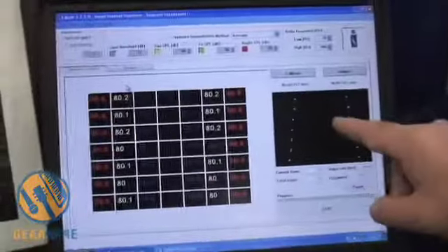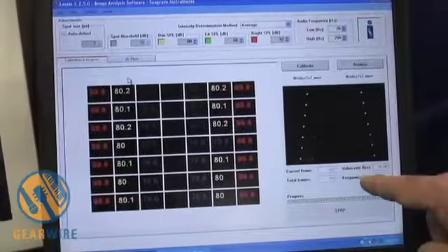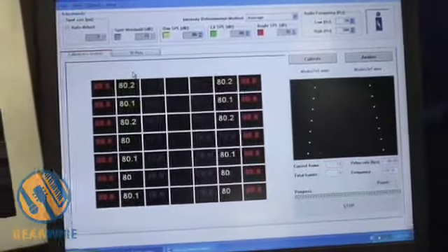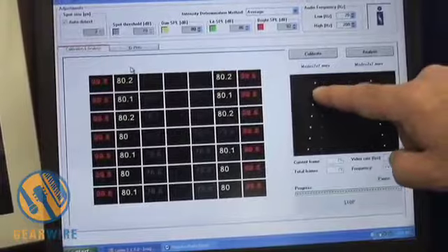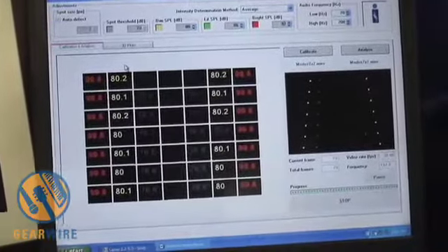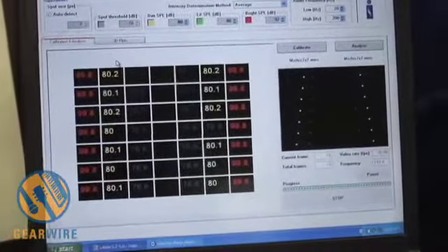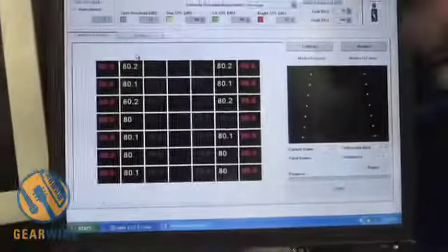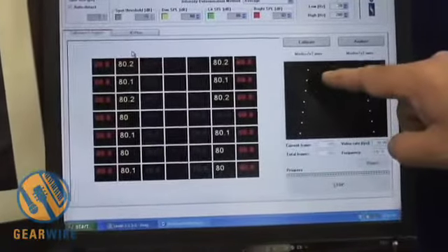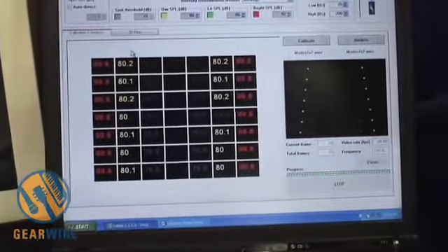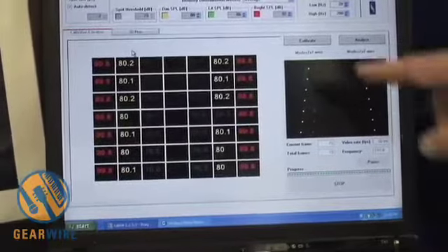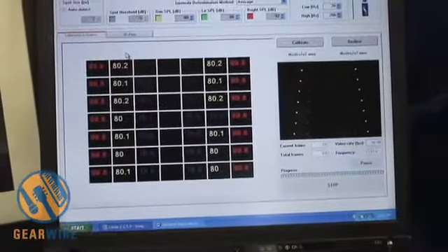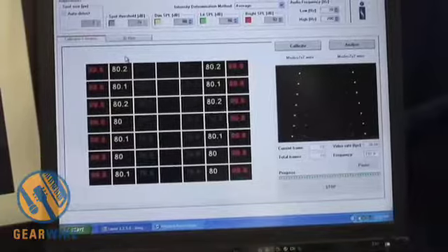Here you can see an array of sensors that are dim in the middle because the sound pressure level is canceling in the center. Each one of these spots on the screen is the video value of a video image of one of the LEDs. So you see the LED here, you deploy them in a room in a 7x7 array, and each spot on the screen in the video represents the sound pressure level at that point. The software analyzes the video frame on a frame-by-frame basis and derives a sound pressure level according to it.